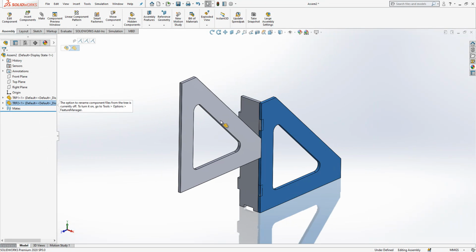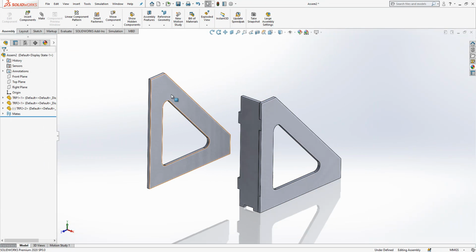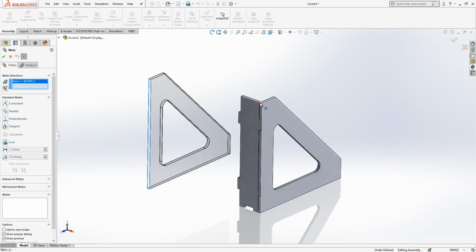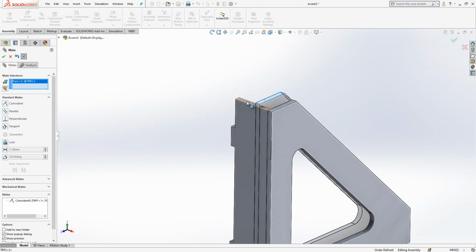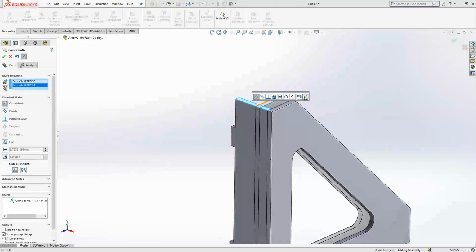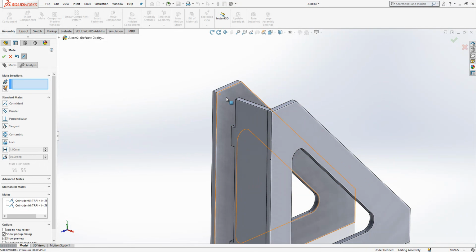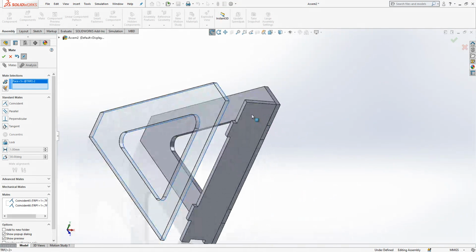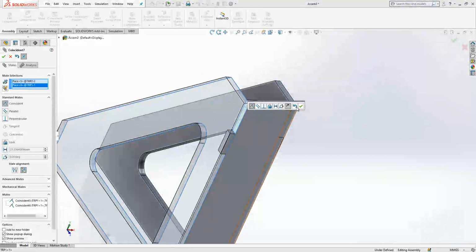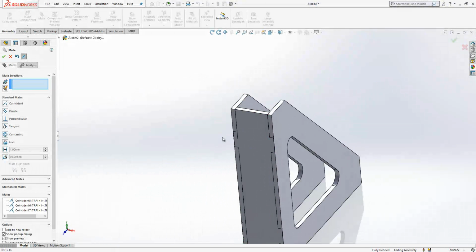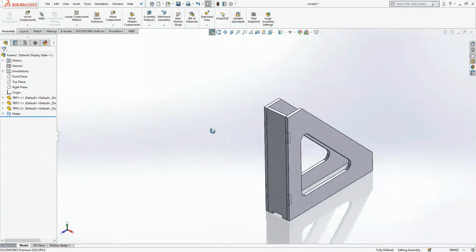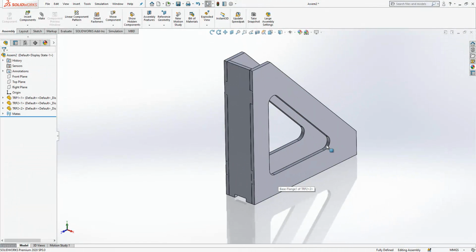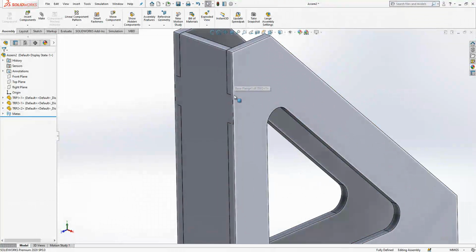And then I will select this one and create one more copy. Same things. We could make a mirror, but now I would like to do it this way. In fact, if you go a little bit deeper, you will not use the surfaces, you will use planes, because surfaces might change, guys, when you are modeling, but planes will not change. And for now, I will skip that idea. Let's keep it like this.